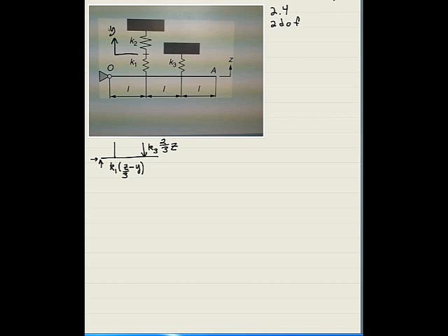Of course, it makes no difference whether you choose z minus y or y minus z, because the next step is to imagine that the thing in parentheses is positive. If it's positive, then z over 3 has moved further than y. And if I move further on the bottom, I'm squashing the spring. If I squash the spring, I'm pushing it. If I push it, it pushes me, and so therefore the spring force goes down because it's a push. So those are the only forces that are acting on this guy.